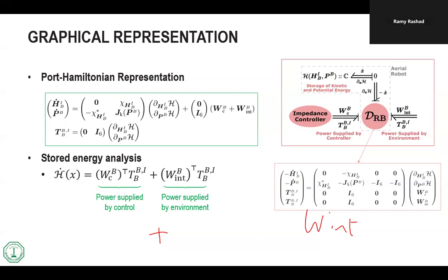Everything we just did with Lyapunov analysis, this idea that I have some energy-like function and it starts to dissipate and goes to zero. But what if something is pumping energy? What if I have something that's continuously adding energy to the system? And this is why passivity-based control is not enough to really work in real life. And this is the topic of the next lecture, inshallah, when we talk about energy awareness, not passivity-based control, but more like energy-aware control. So this is the new paradigm that we're going to be talking about next time.